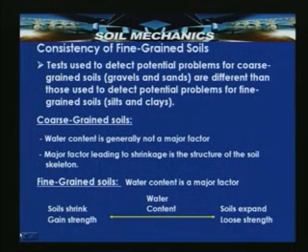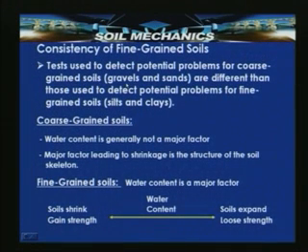So, tests used to detect the potential problems for coarse grained soils, basically gravels and sands, are different from those used to detect the potential problems for fine grained soils, basically silts and clays. For coarse grained soils, water content is generally not a major factor.